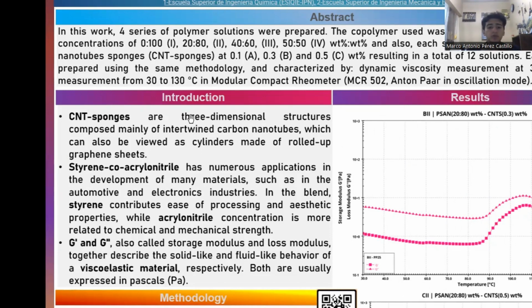First, to understand what carbon nanotube sponges are, it helps to first understand what carbon nanotubes are. These are allotropes of carbon, just like graphene. In fact, it is easier to visualize a carbon nanotube as a cylinder formed by rolling a sheet of graphene around an axis, and sponges are very similar structures with the addition of boron, resulting in the branching of multiple cylinders. These branched nanotubes have interesting mechanical and electrical properties that are incorporated into the mixtures in which they are used.